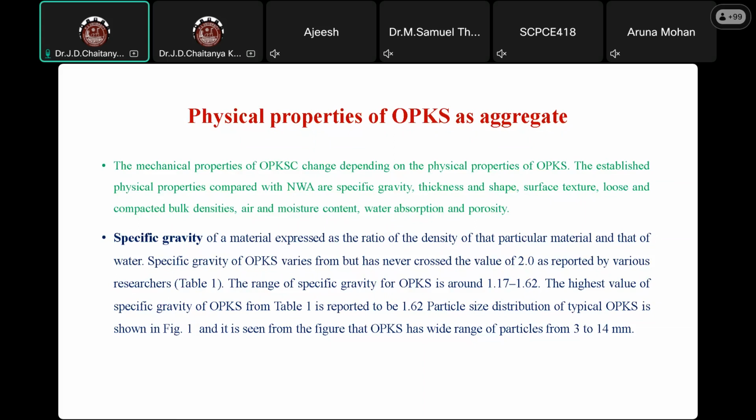Okay, the water absorption is more. We have some methods to reduce the water absorption also. You can go with a PVA solution, polyvinyl alcohol, and coat all the shells with it, and then we can use the shell. Also, you can soak the shell in water the day before using it in the concrete. We can go with the optimum temperature, that means we can open it to the sunlight, and the moisture content will be reduced. So the shell already has enough water given, and after that we can use this shell in concrete production.